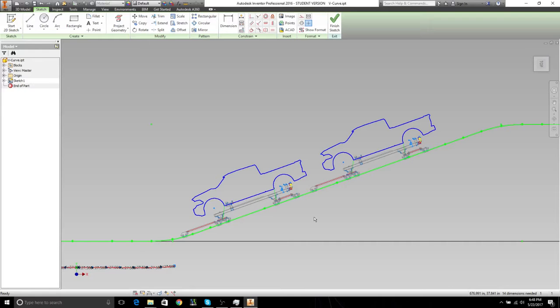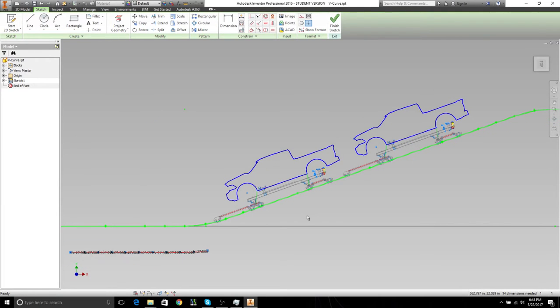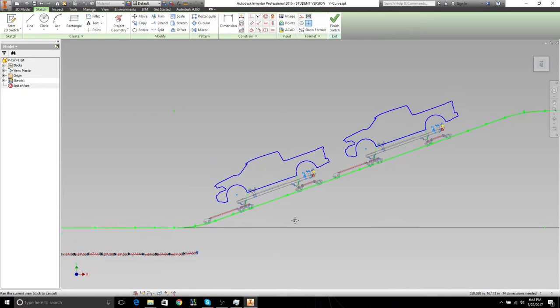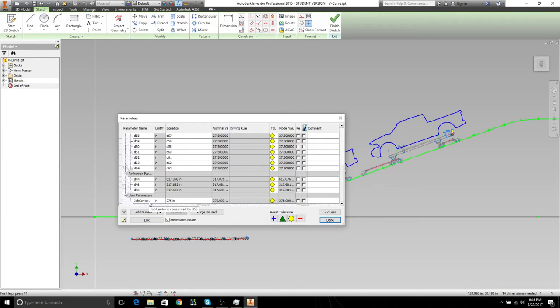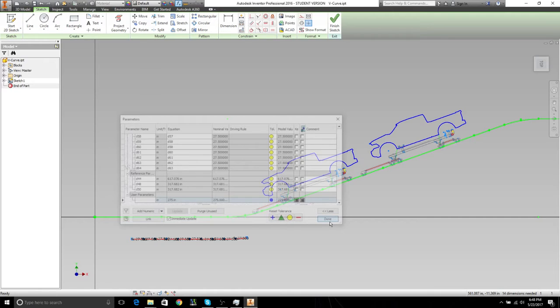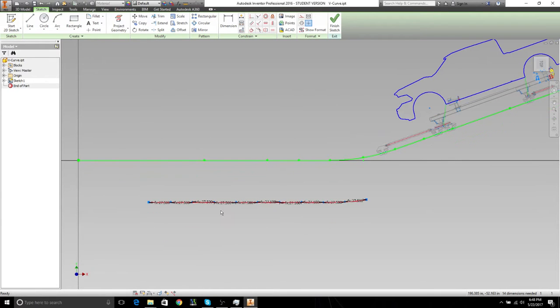However, these carriers right now are moving independently from each other, but in a production study, the spacing between them has to be determined by a set job center distance. So, if you recall in the last video, there's this job center parameter that determined distance, and we also have that here, but in this case, that job center is controlling the length of this spline here.